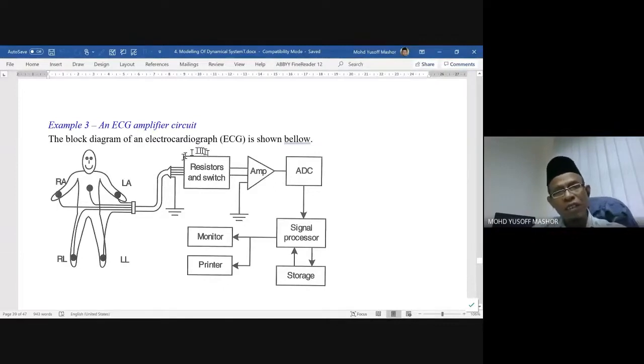So after we connect to the conditioner circuit here, the output becomes clean and manageable. Over here it is very raw, so it's very difficult for us to see the signal. After the conditioner circuit, the signal is clean. Then we put it into an amplifier, so that it will be up to the normal operation of the processor, which is normally within 0 to 5 volt.